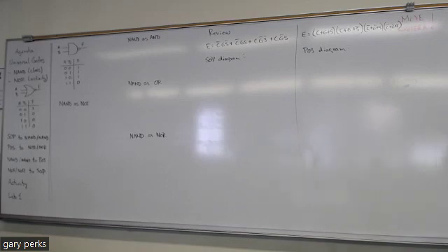And lab one, the lockbox lab, right now, you can do two of the outputs. You can have an SOP output and a POS. And remember, we want those outputs to be the reduced expressions, right? So just like we talked about last time, you have to do a K-map and get the reduced SOP and also the reduced POS.